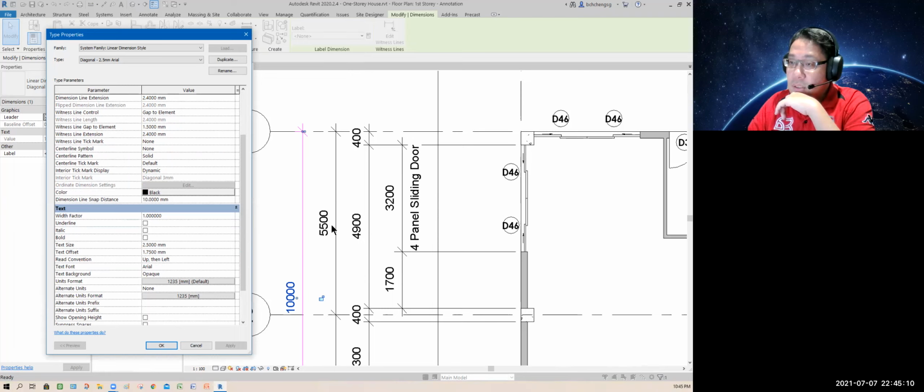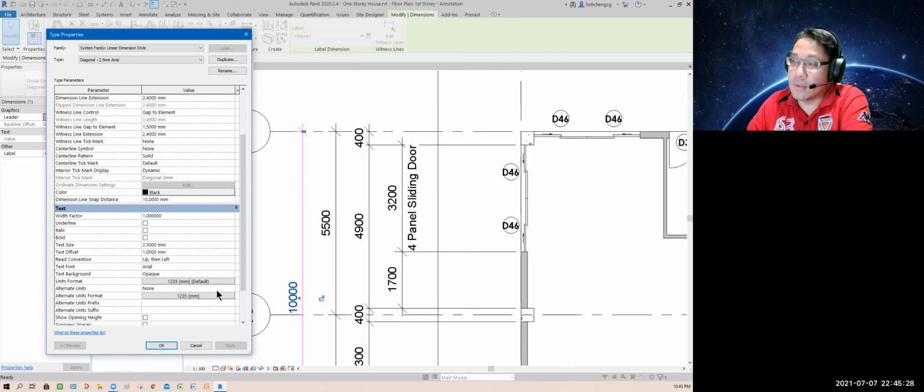This space here is 175. And with your text boundary itself, it bounces further. So change it. Set to 1, apply, and see what happens. See the shift closer. Not satisfied, change again. 0.5 and see what happens. See? Better, right? So all this can be changed.